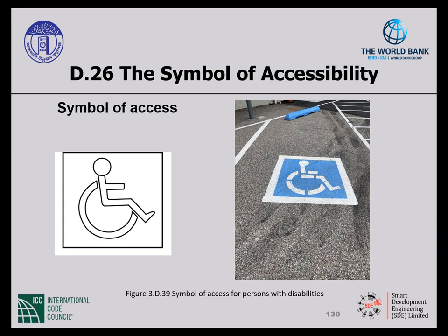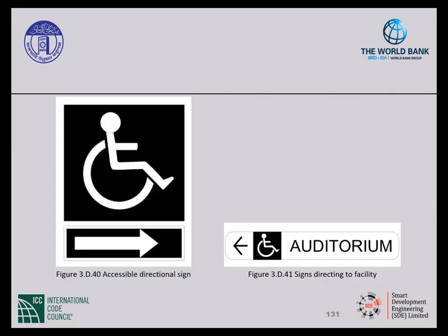Accessible buildings shall have symbols posted at the front road, inside premises, accessible parking, accessible routes, and the entry to the building. Also, you need to think about directional signage anywhere there's a change in direction: in a main lobby, in a passageway, in a lift, entrance, toilet, car parks, anywhere. The directional signage with destination indicated is shown on the right, and it should be used where the location is not obvious or is distant from a current viewpoint.